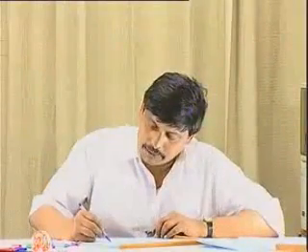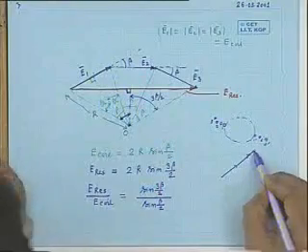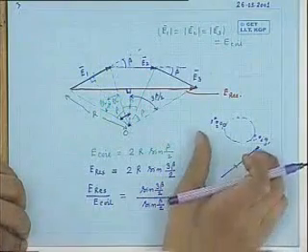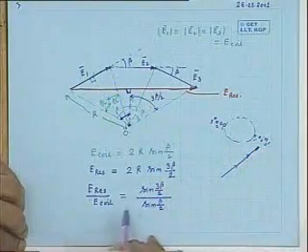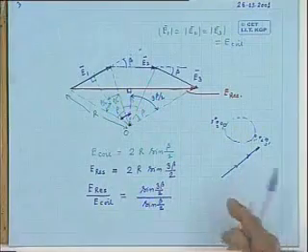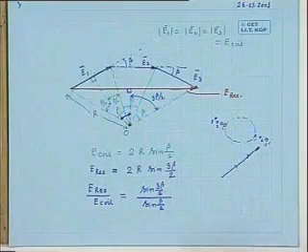Then what will be the resultant voltage if the coils were connected in series? The voltage induced in coils 1, 2 and 3 would have been in the same phase, and the addition of these vectors would have been this plus this plus this. So what would have been the resultant voltage? 3 E coil. So 3 times E coil is the voltage that one would have got if the coils were not distributed in space but were concentrated in a pair of slots.